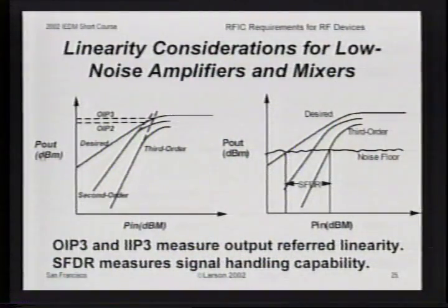Now, the second absolutely crucial thing for low noise amplifiers is the linearity of the device. And Professor Abadi gave a very nice overview of linearity considerations in receivers in the last talk, so I won't belabor this. But essentially what we want to do with the receiver is maximize the distance between where the desired signal, this is on the receive side now, pokes up above the noise floor and can be seen with a decent signal-to-noise ratio, and where this large jammer or a large undesired signal also pokes up above the noise floor at the same frequency.